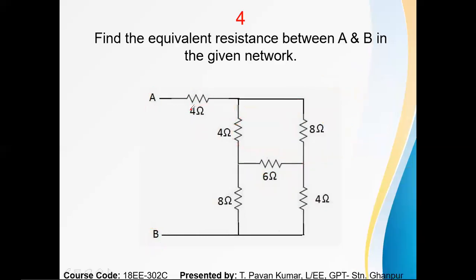Next. So here, what about this 6 ohms? Is 6 ohms parallel to this? No. Series to this, because the same current is traveling through this? No. Here there is not the same current. After current comes from here, it is going to split like this, here and here. These both are not parallel. These both are not series, and 8 and 6 are not parallel.